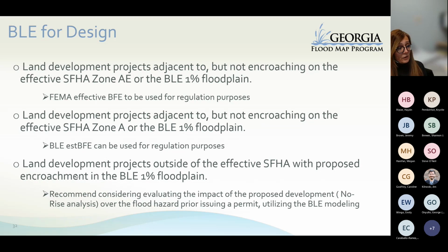A third scenario is if you have a proposed development which is outside of the effective special flood hazard area, but it's proposing an encroachment on the 1% base level engineering analysis floodplain. In this particular case, we recommend considering evaluating the impact of the proposed development over the flood hazard prior to issuing a permit.